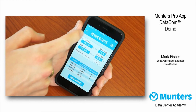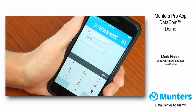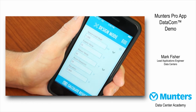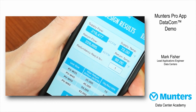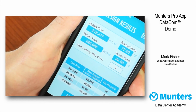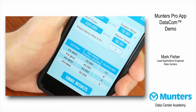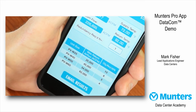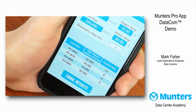I'm going to go back, and I'm going to change the elevation of this data center from sea level to 3,800 feet. And now we'll see that the required actual CFM has gone up because of the lower density. And looking at our table of options below, we see now we would actually need 6 W40s or 5 W50s to be able to meet the same load as before because of the higher elevation.